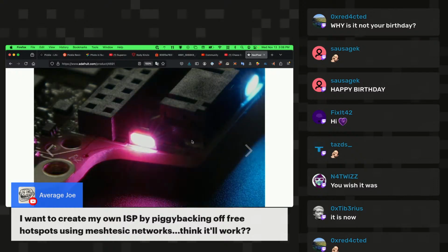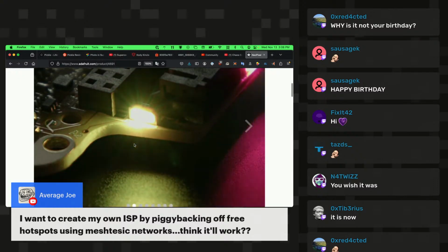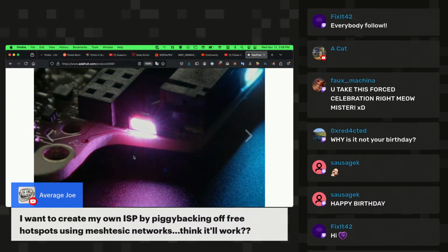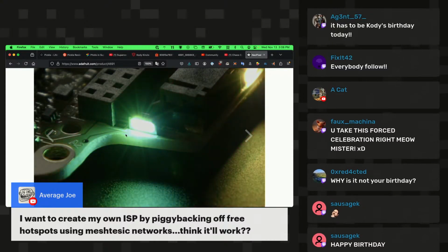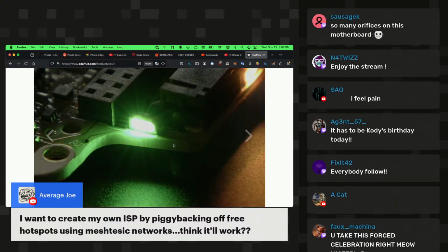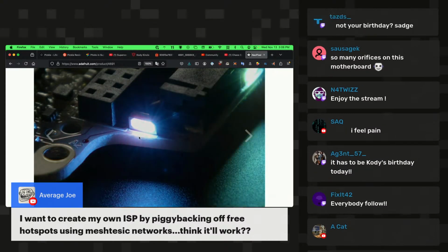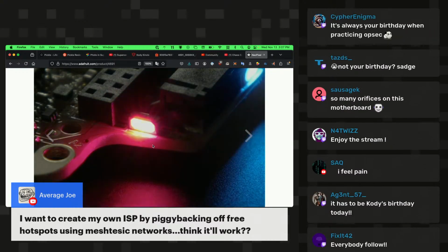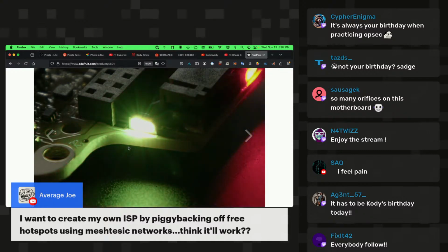And we already saw this on the Hackaday SuperCon badges. They were able to create these incredible badges, or I guess they were simple add-ons that glowed through the center, and they were using these side-mounted LEDs. That's because this kind of PCB art isn't super common. If we want to use something like this, it would be relatively difficult to have this LED mounted straight down, even though we can create a design in KiCad that allows a glow-through board that depends on an upside-down LED.